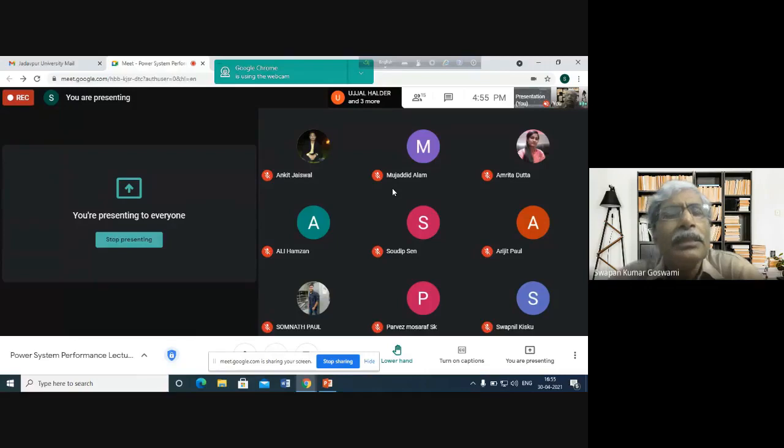As a result, power will be consumed. This ionization will require power, so it will be consumed from the generator, from the system. So air will be ionized. As a result, there will be loss of energy, and the effective diameter of the conductor will increase, and this is not a desired situation. Okay, so this is called corona.